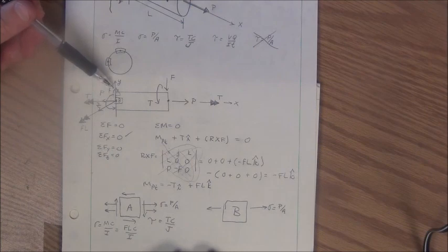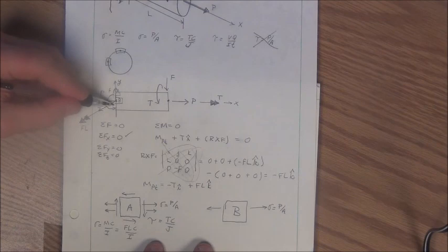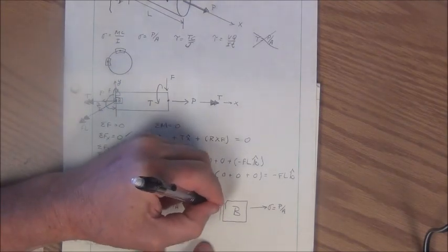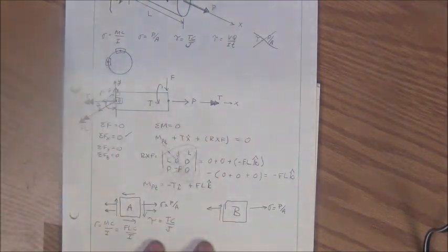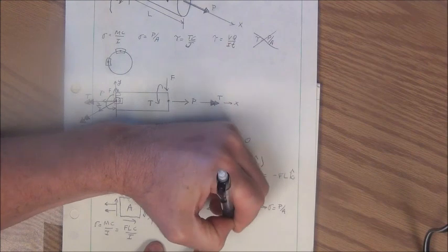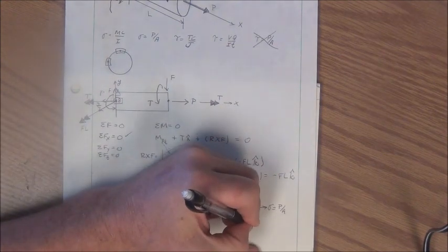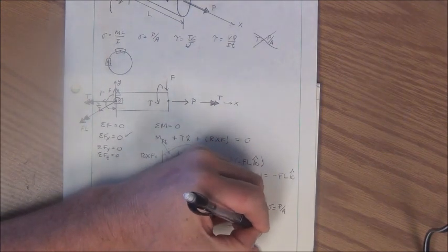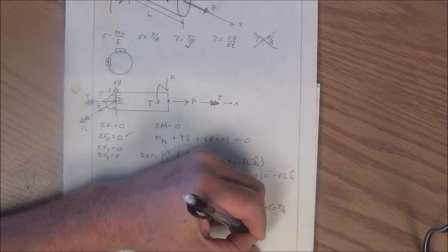The load F in the vertical direction now is parallel to this face here at B. So it's going to act right along that. It's parallel to that face, and that will cause a shear due to bending. So this would be a tau is equal to a VQ over IT.